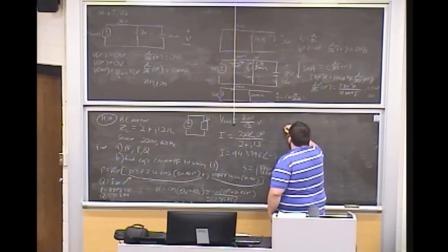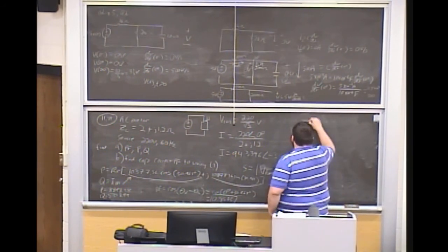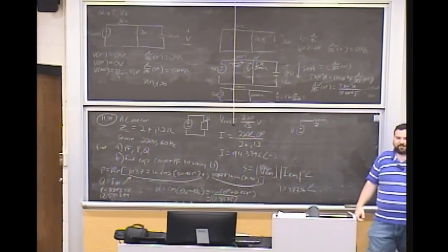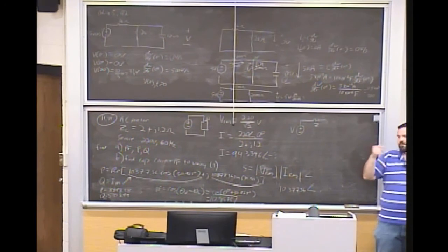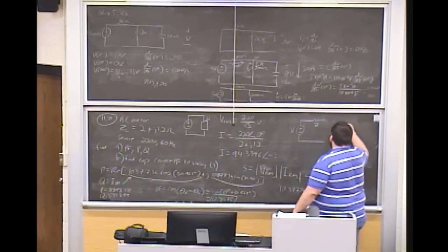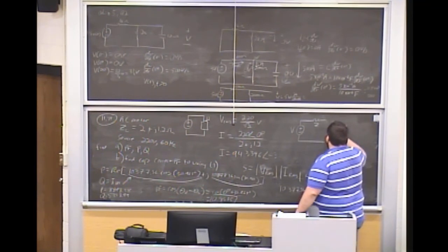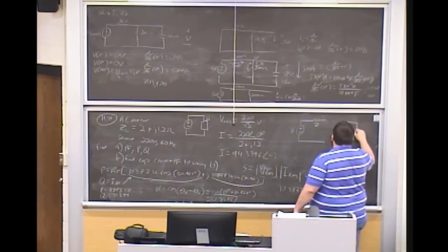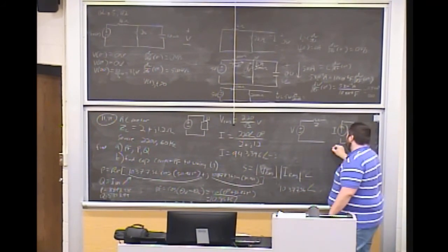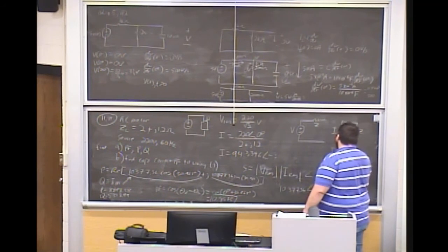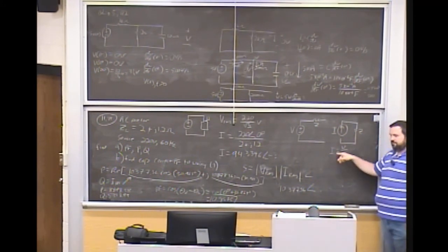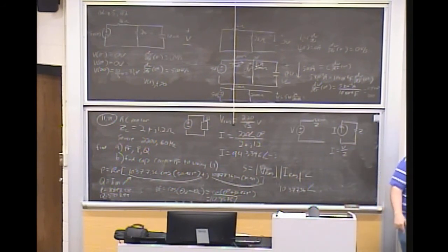So if you have a voltage source and any kind of Z value, that could be capacitance, inductance, or some combination, you can do a source transformation to convert that to an I in parallel with the same Z. You just make I equals V over Z. Now, of course, if I had an emboldened font, those would be phasors. You just have to do the phasor mathematics.